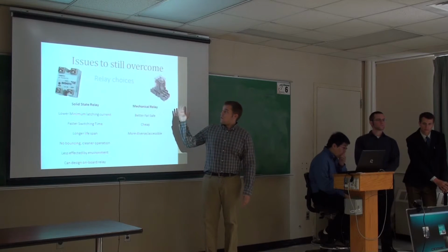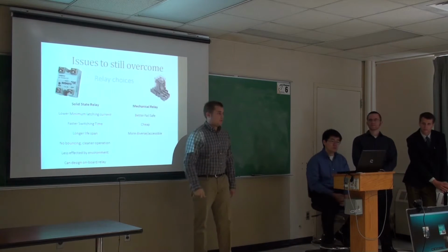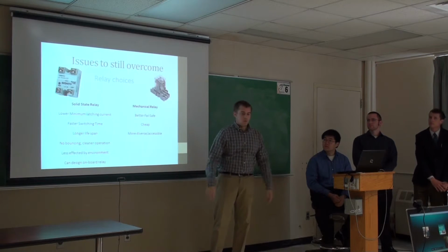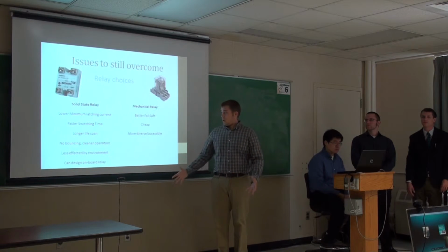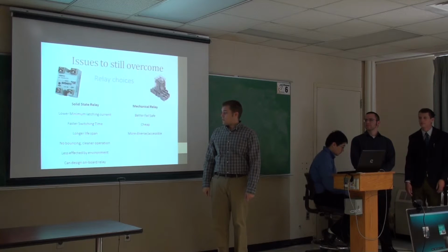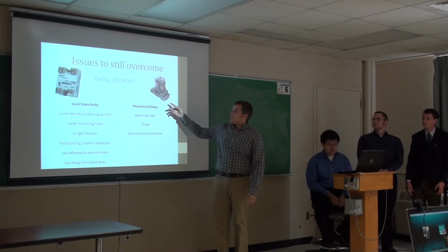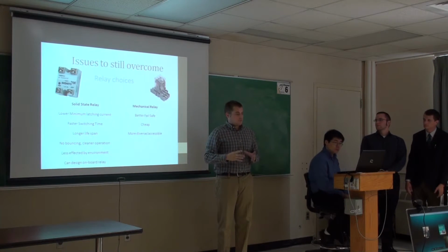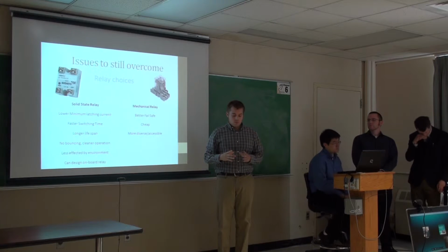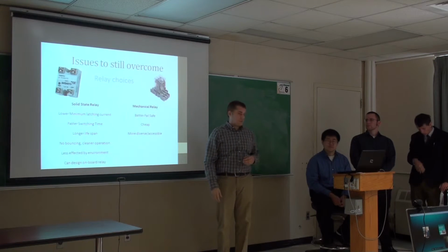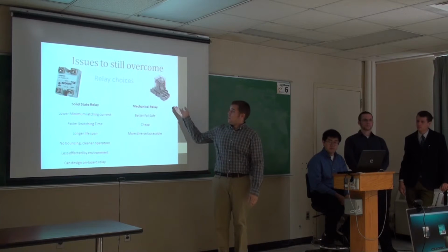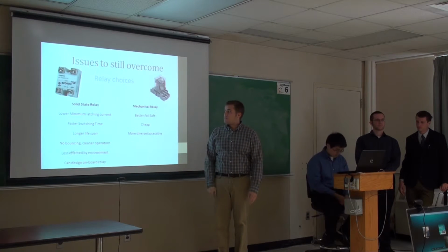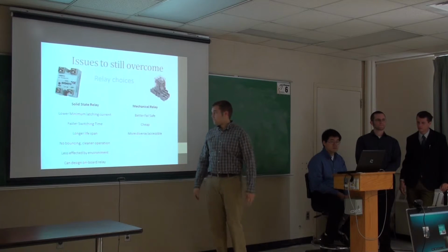The problem with our relays right now is that they wanted 125 volts, 10 amps, which is over a kilowatt of power, which is quite a lot of power to send through this device. So these options become really large in size when you start doing large amps like that. So we want to meet our 12 cubic inches measurement, but these options are kind of messing that up because they're really big in size.